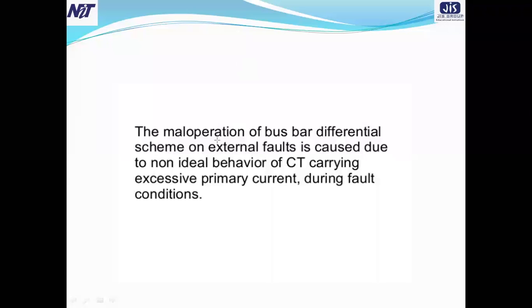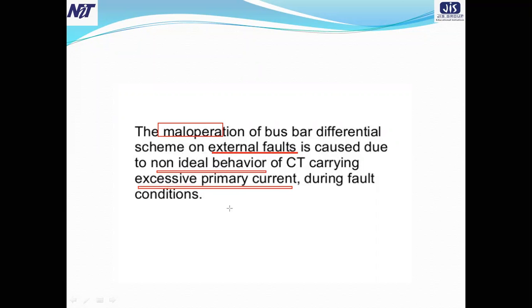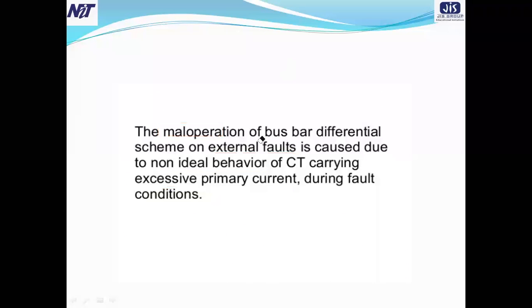You need to remember that the maloperation of the busbar differential scheme on external fault is caused due to non-ideal behavior of CTs carrying excessive primary current during fault conditions. Need to remember this part.